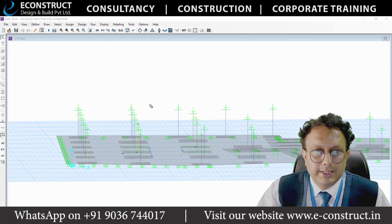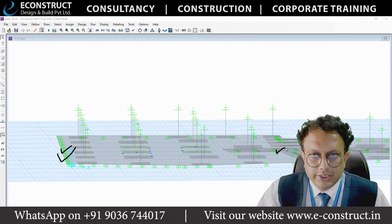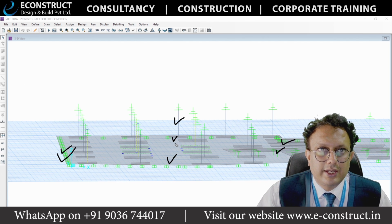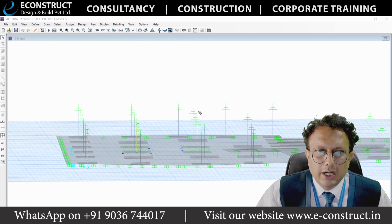But this is basically the combination where a raft is there. You can see that there are area springs. You can see that there are point springs. You can see that there are columns. There is a slab or the foundation pad. As well as you can see that there are the pedestals, the raft pedestal also is there. Understood. So this is how, in a little complex way, we go through the different types of foundation systems. All right.